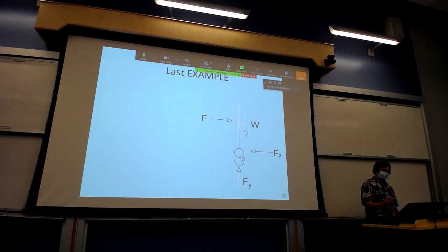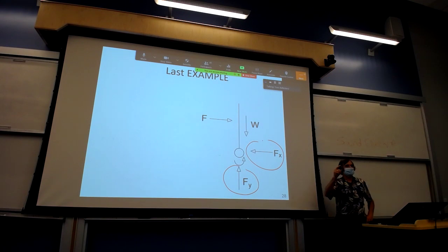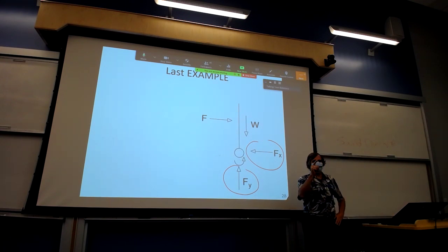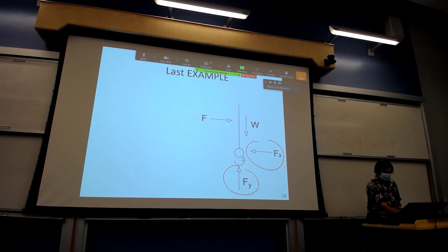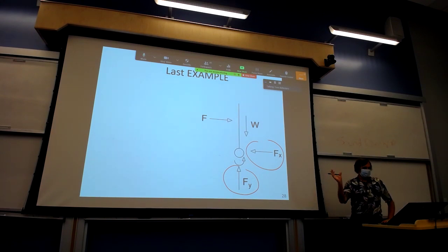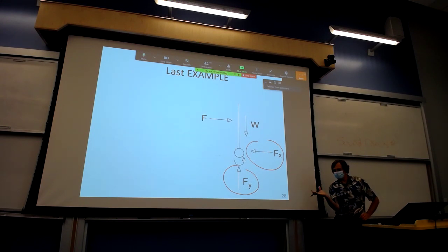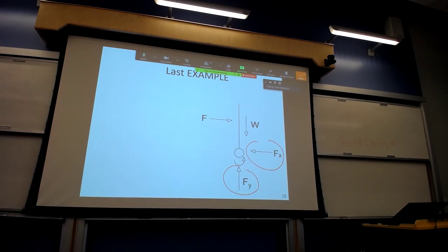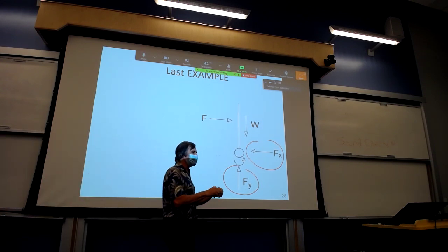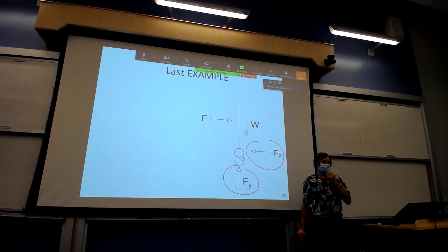Never forget, when you have a hinge and a connection, there are also forces acting at that hinge. So if you just did a force balance and you ignored that, you're applying a moment at that pin connection. But without Fx, the whole system can move horizontally. So the gate's not swinging open, but the whole system's moving this way, right? Why? Because you didn't apply Fx, a restoring force. And Fx and Fy are forces that are applied at the hinge.